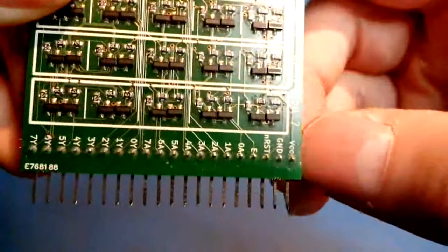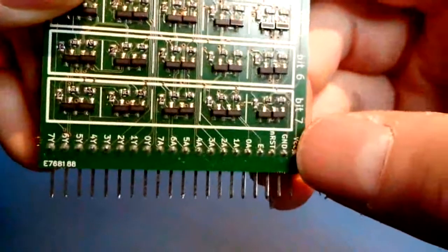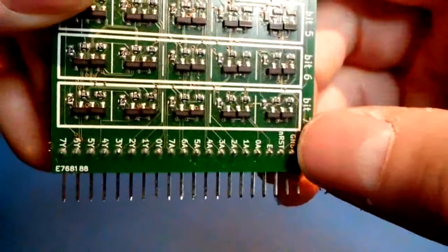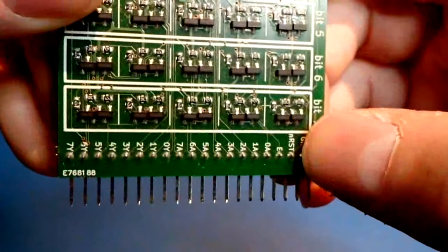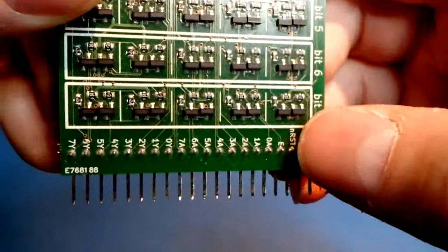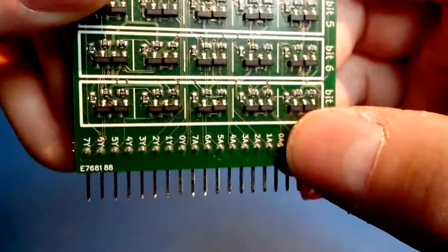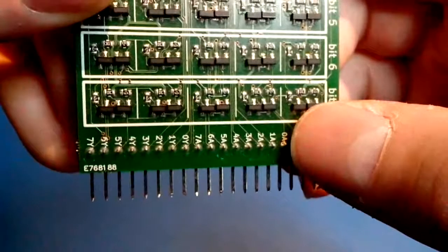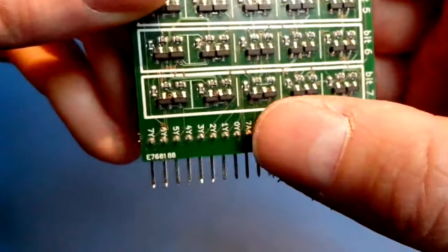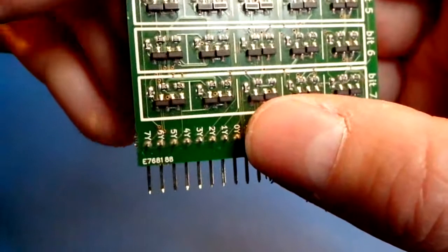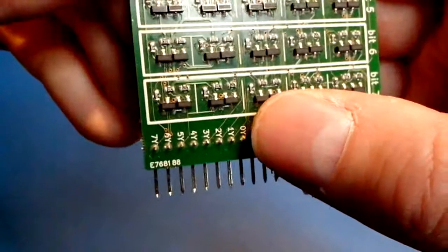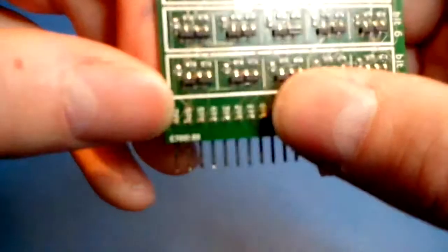If you look at the inputs of this board, you will see the positive and a negative input, the VCC and the ground. It has a low active reset input, an enable input, and for each bit it has a data input labeled A, so 0A until 7A, and for each bit it has an output labeled Y, so there's 0Y until 7Y, as you can see. It's basically the same subcircuit 8 times.